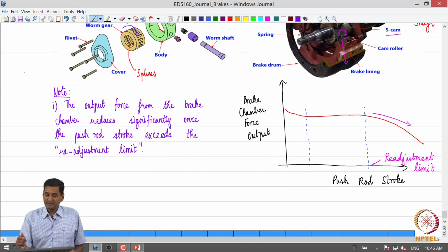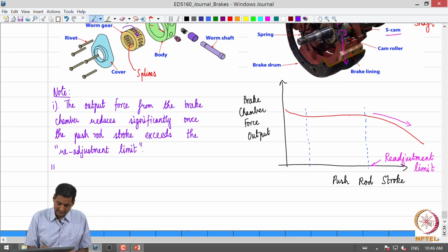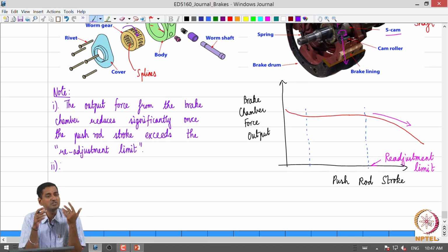There is another point which is important as far as air brake systems are concerned. In the presence of a leak in an air brake system, the sensory feedback available to the driver is lower than in a hydraulic brake system. As we discussed, in a hydraulic brake system, if there is a leak in the fluid circuit, we will see that our pedal is going to become softer, a pedal sinkage effect, right.